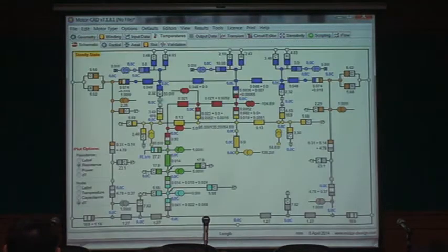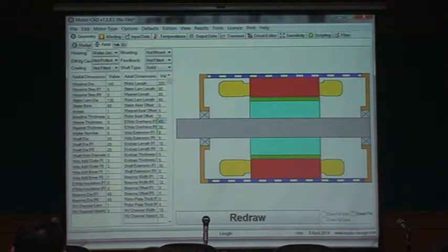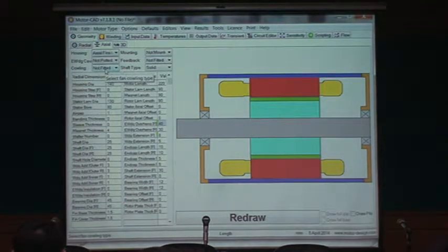And if I look at it here, well, now I'm overcooling my motor. It's only 33 degrees. So basically I'm killing it off here. I don't want to do something like this. This machine would not require obviously a water jacket. There are some better things to do. So probably if we do some better things, or in fact let's do the fins the other way around.